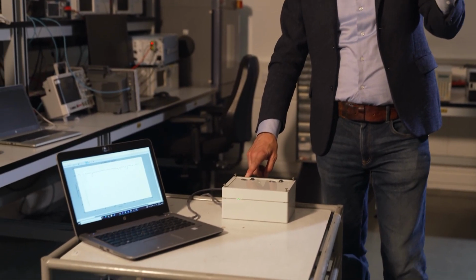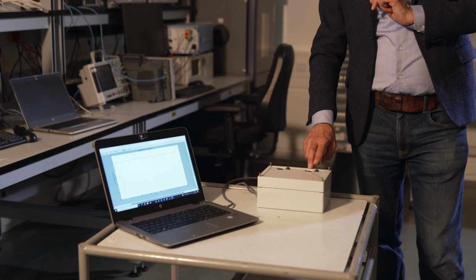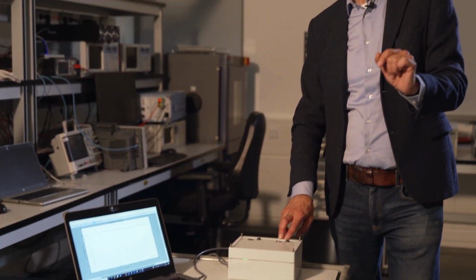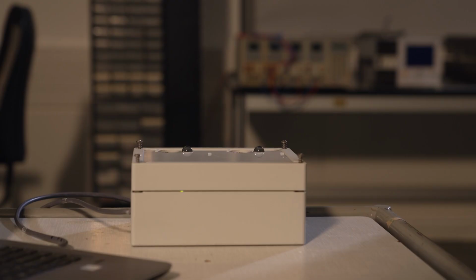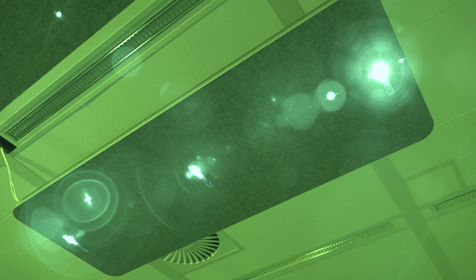But we can go even further, because in fact this detector sees a mixture of multiple light sources in the ceiling. The other detector will also see a mixture of light sources, but a different mixture. Because of these differences, a mathematical operation can separate them such that we have clean lines of sight. The first line of sight can carry the first part of the data, the other line of sight can carry another part of the data, and thereby we increase the throughput of these optical wireless communication systems by distributed MIMO.